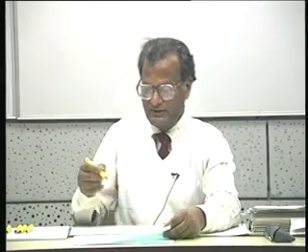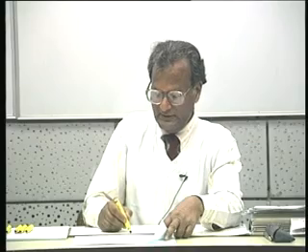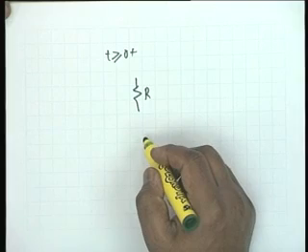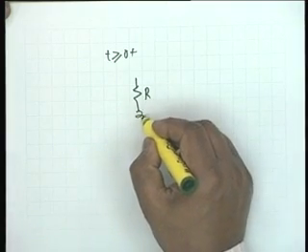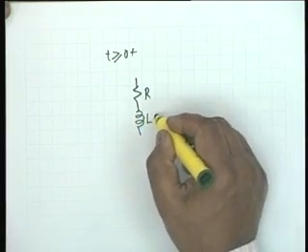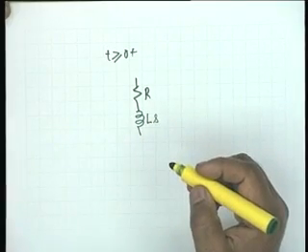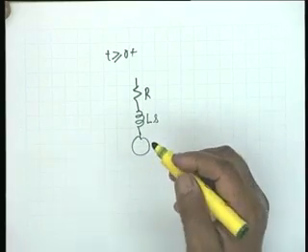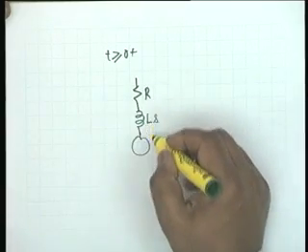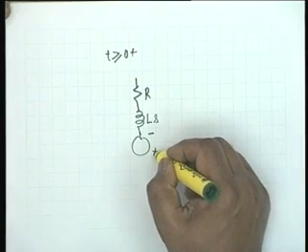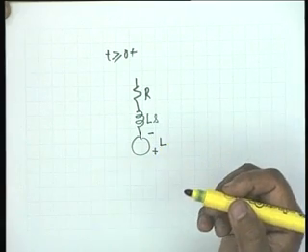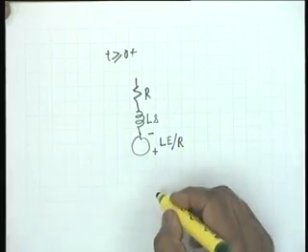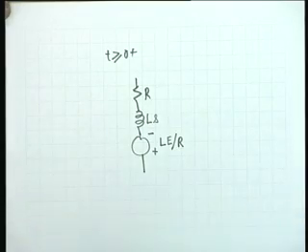If you draw the transformed equivalent circuit for t greater than or equal to 0 plus, obviously what we have is R, and then the inductance L, multiplied by S, its impedance, and then you have a voltage generator. This is the Thevenin equivalent circuit in the opposite direction, that is minus plus, L times IL of 0 minus. IL of 0 minus is E by R, and therefore L E by R. This is the equivalent circuit for the inductor.